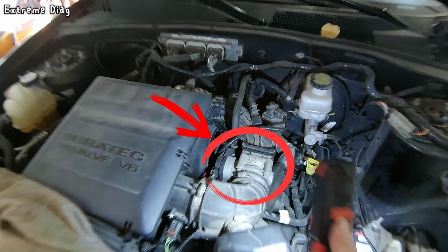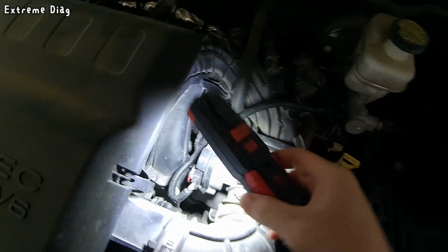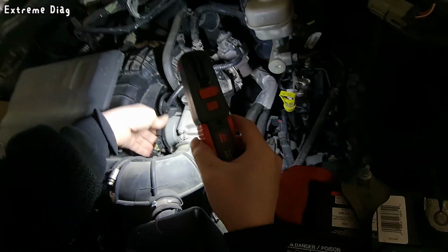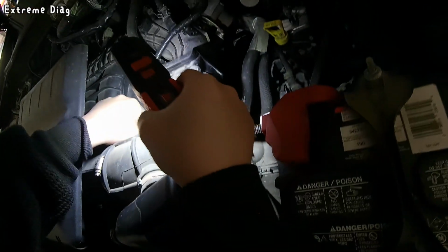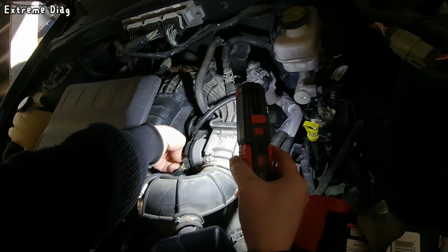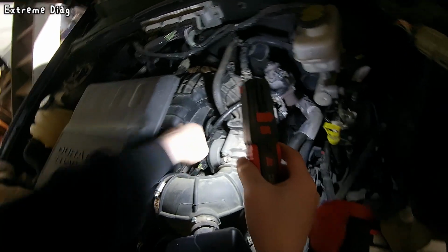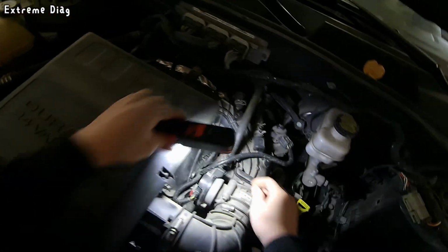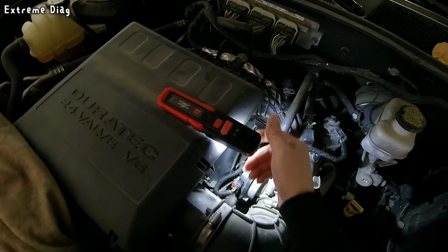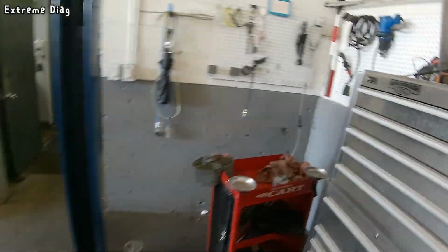We've brought the car into the shop. This is the throttle body. Before diving deep into diagnosis, I'll start with a basic inspection. First, I'll disconnect the throttle body connector to check for visible issues like corrosion. It's too tight to get a good grip with my fingers. I'll use a tool to disconnect it.